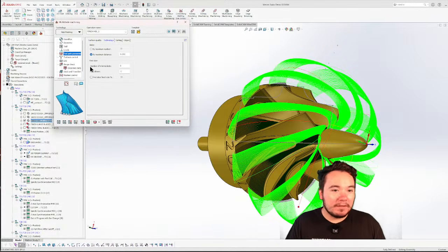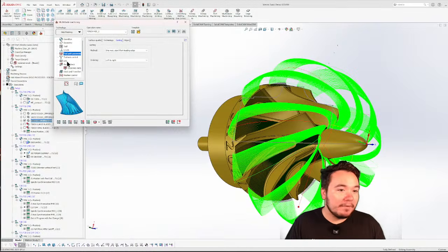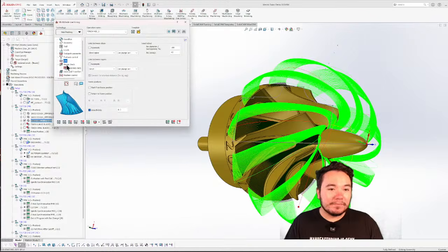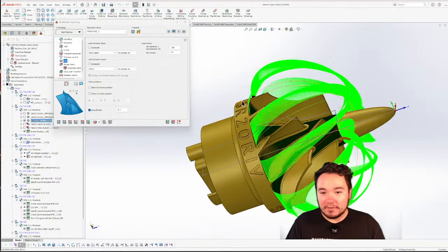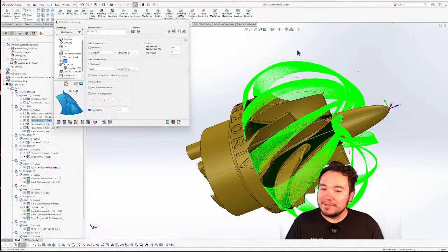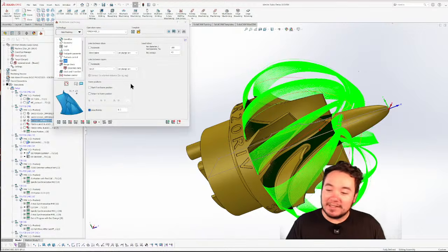I did mess with the step over. You know, it's 2 thousandths to get a really nice surface finish on it. Left to right ordering, pretty much standard, just as the roughing. Yeah, this one does have blend spline direct, so it should be moving pretty fast over there. Also kind of looks cool with how it gets off the cut. Could be wasting a little bit of time, but this is a show part. You have to keep that in mind.